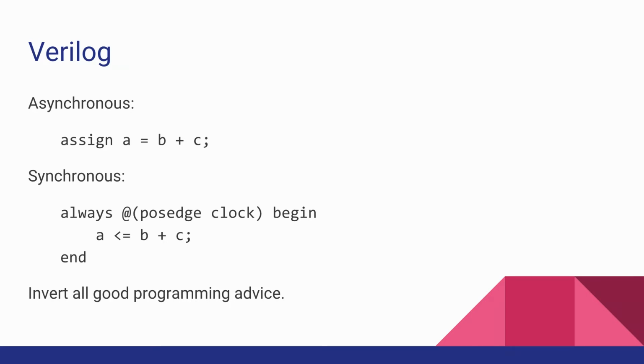All logic on chip have to run at the same clock rate, or do you have different modules running at different rates? You can have it running at different rates, and I've got a slide later about why that's not a good idea. But let's say in this case, let's say that B plus C was too complicated, and it was going to take, let's say, 1.5 clock cycles to do. What you would do here is you would have an if statement right over here saying like if the clock is odd or whatever, then latch it. So every other clock cycle you would just not latch anything, and you would latch every other one. You're allowed to latch every other one if you want to.